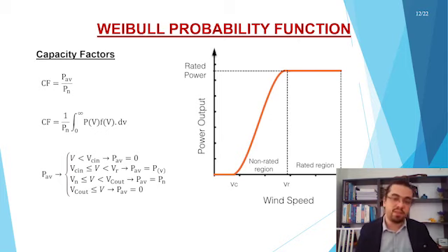In another case, I can express the generalized formula. As you can see, the first formula is average power output divided by nominal power. Based on this, the method of calculating the capacity factor with the variable is the second function. As you can see, our nominal power output is here, and however we need to use the variable probability function and wind turbine power output function to calculate the power output we have obtained.